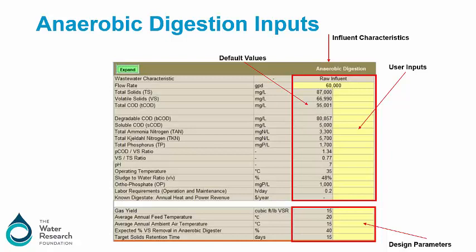This value is typically between 13 and 17 for anaerobic digesters. Minimum SRT for Class B biosolids is 15 days. The recommended SRT is 15 to 30 days. If digestion is being done for nutrient recovery and not biosolids quality, 15 days is recommended.